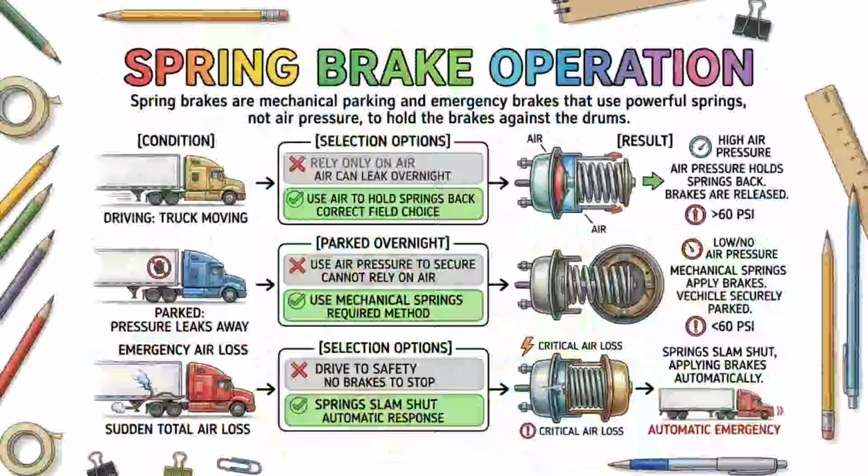Because the air compressor pulls in normal outside air, it also pulls in moisture and sometimes a tiny bit of compressor oil. When the air cools down inside the storage tanks, this moisture turns into liquid water, which collects at the bottom of the tanks. If you leave water in the tanks during freezing weather, the water will turn to ice, block the air lines, and cause complete brake failure. This is exactly why you must open the drain valves at the bottom of your air tanks at the end of every single driving day. Test questions frequently test your knowledge of daily manual tank draining.